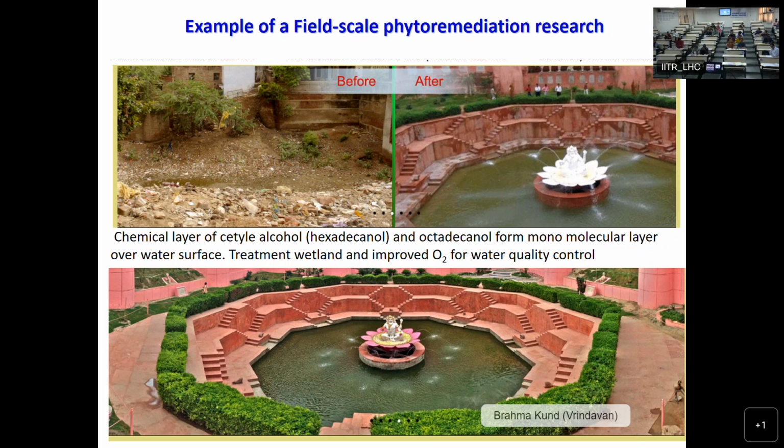As it's an external process, or we can say an artificial process, is there any negative effect of it on the ground? Mostly with bioaugmentation, when we apply it, the threshold time, the starting of the degradation, is also important. As soon as you introduce a new strain of bacteria to the site, they will not start working. They need some acclimatization time.